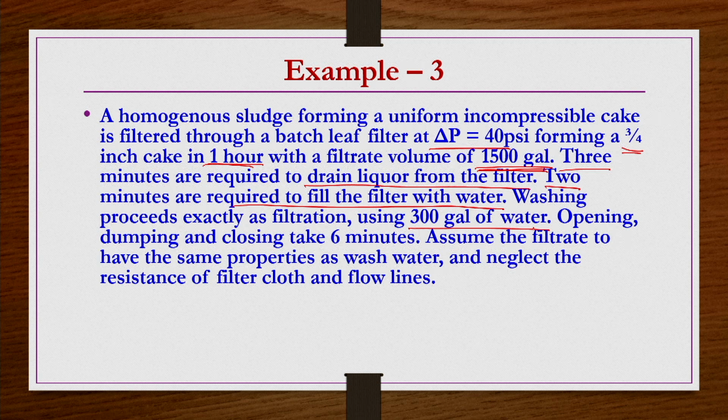Opening, dumping and closing of this filtration process takes approximately 6 minutes. Assume the filtrate has the same properties as wash water, and neglect the resistance of filter cloth and flow lines, that is Rm is negligible.